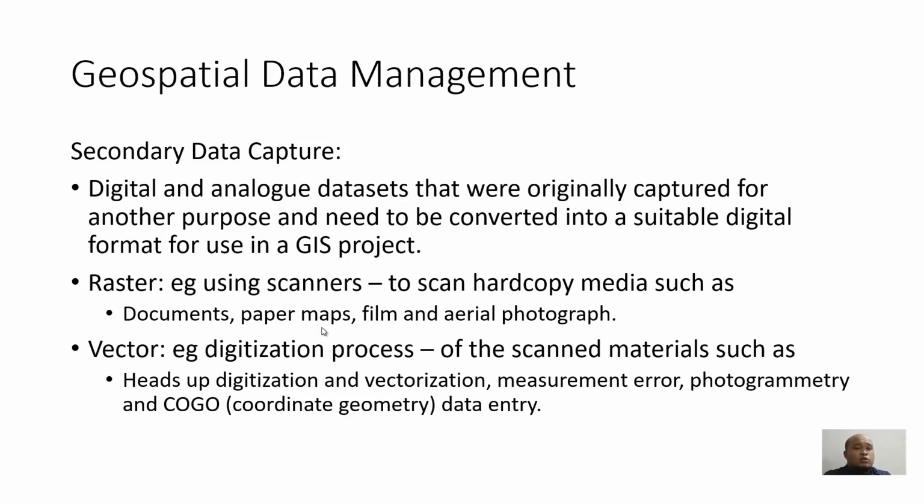And we also need to be particular about measurement error, whether the error came from the primary data collection or from the scanning process. You know, sometimes the aerial photograph is very old and already distorted, or the document is already distorted. So those measurement errors need to be tackled.